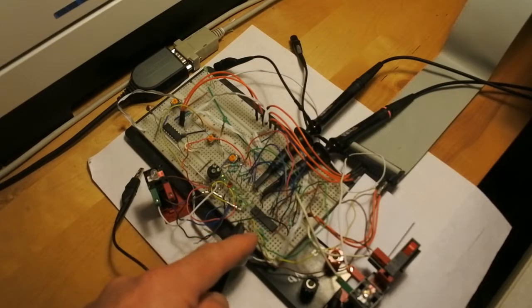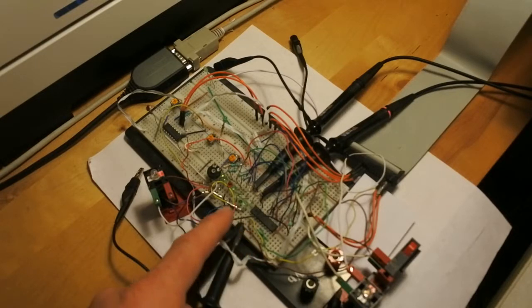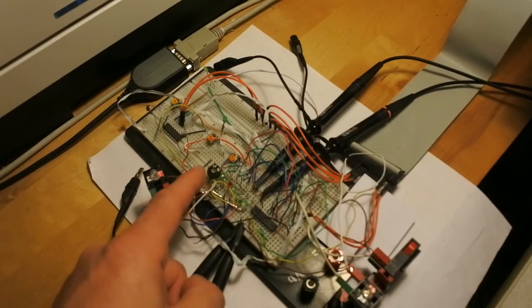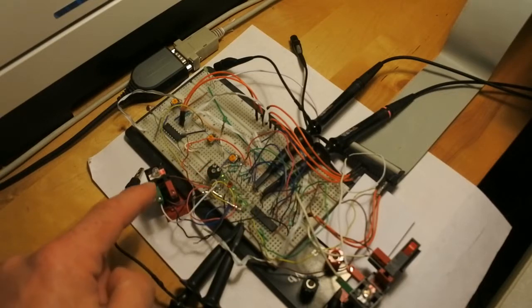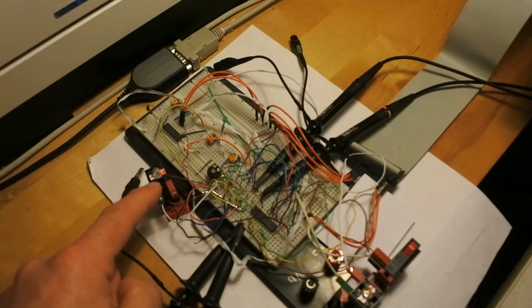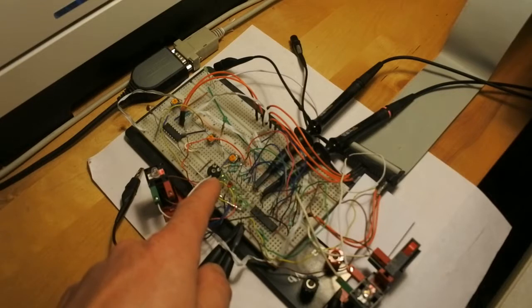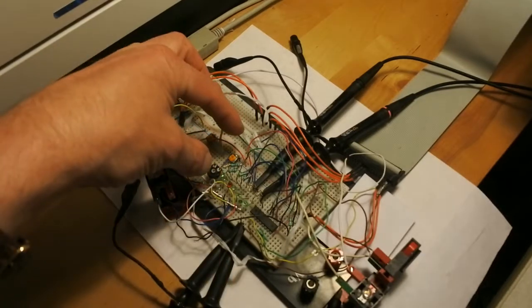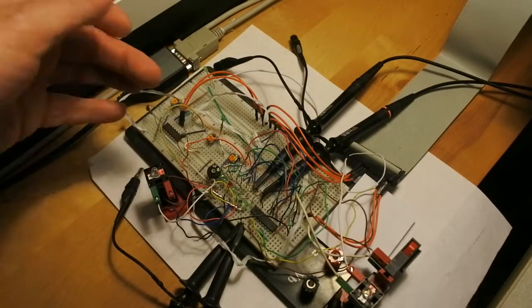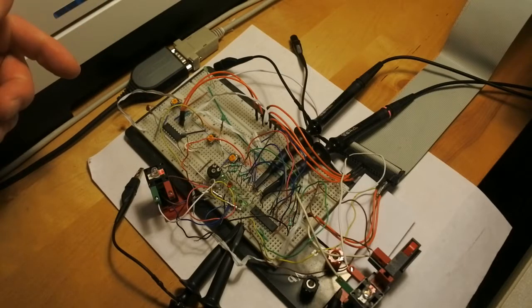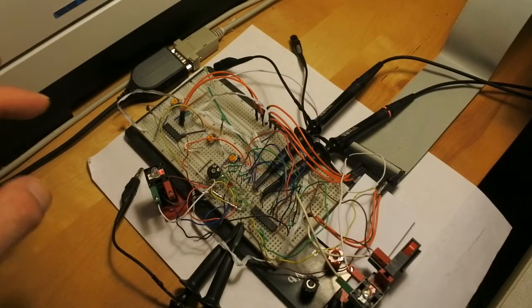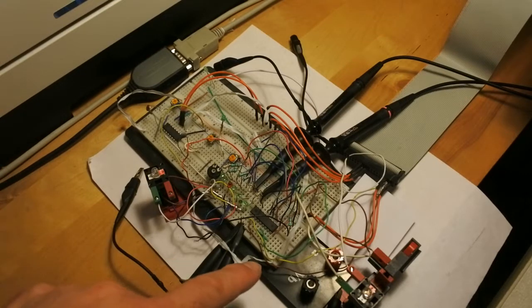And in this case, for this project, which is programmed in standard C, I use the MCP 23008, which is an I2C extension, and it controls these series of LEDs, including this one. This is the 8th LED. Had to do that because this project for SPI, serial peripheral interface, also programmed in C, was set up a bit wider. Anyway,